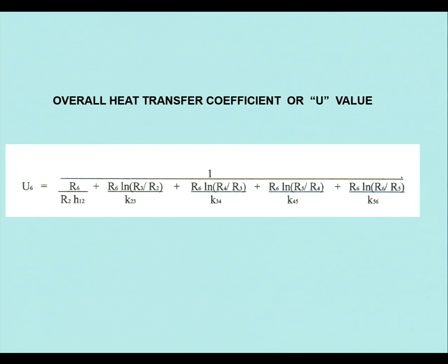Now that surface area will be different if it's the steel inside diameter of the pipe, the outside diameter of the pipe, the inside diameter of the coating or external diameter of the coating. You have to be careful. Normally what we do is it's safer to use that where that area is the internal diameter of the pipe, because that's the outside diameter of the product.